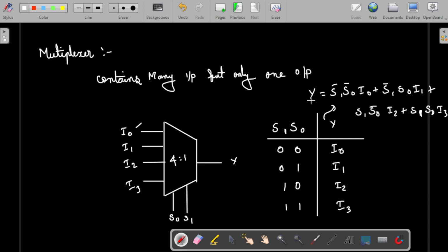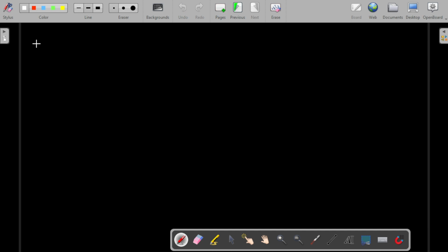So this is how the logical function output will look. Okay, so let's see, we have already seen universal gates, right? So whether MUX can act as a universal gate is an interesting question. We know that a universal gate is something with the help of which we can do any kind of function. So let's see whether MUX can be used to do all these operations.